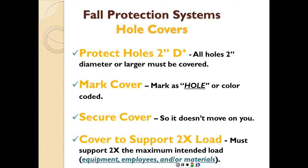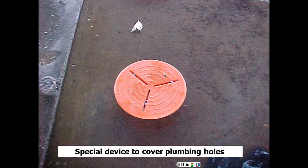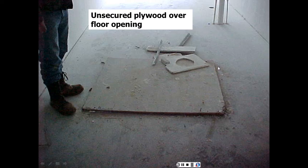Secure the cover so that it doesn't move on you, and cover to support twice the load that's going to be imposed on it. So if a person is going to be 180 pounds, for example, then this cover of the hole has to withstand a force of 360 pounds. So here, for example, we have a hole that's about maybe 4 inches in diameter. This should be covered. And here's the good cover that has been fixed in place with nails to make sure that it's not going to move.